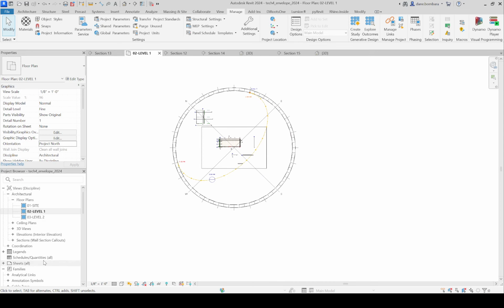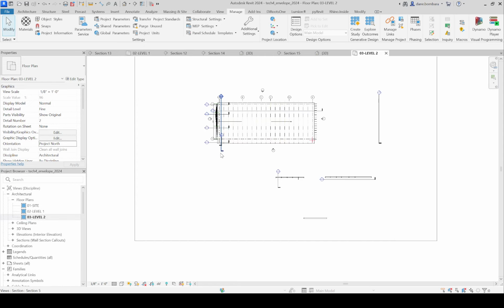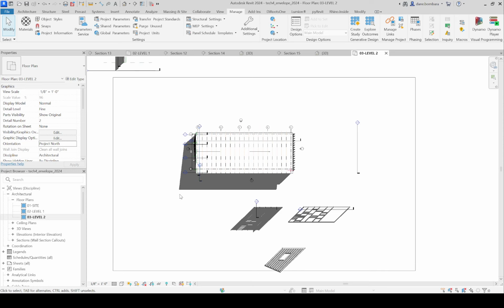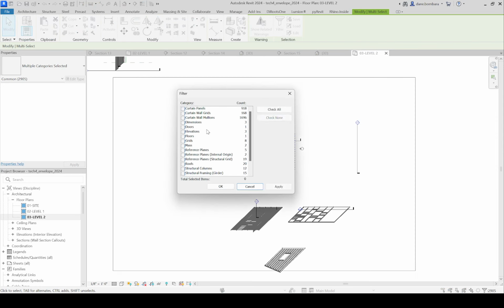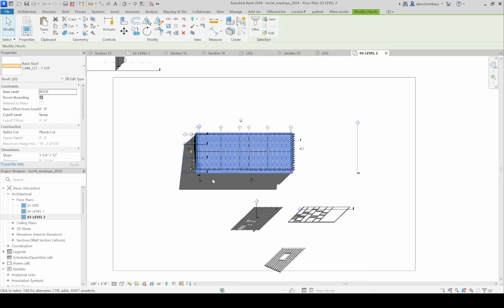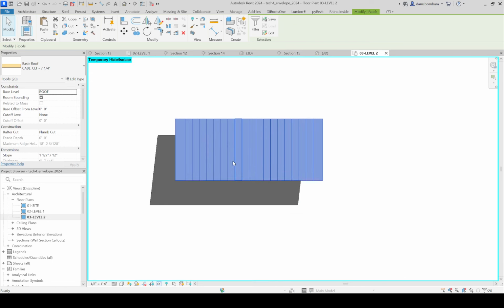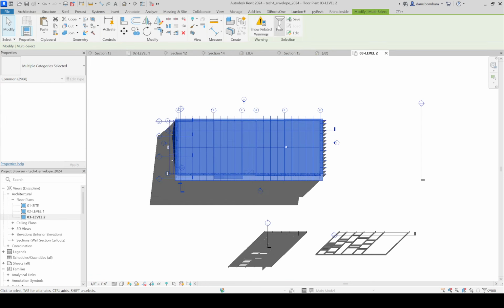And then the other thing I wanted to show quickly was that if you want to do a planned sun study, like you want to look at your space and see how shade and shadow and light are passing over your floor plan, you can't just, if you click on this level right here, I'm looking at a plan of my roof. If I just select all my roof members here and I hide them, oops, I isolated them. I want to hide them, hit everything else.